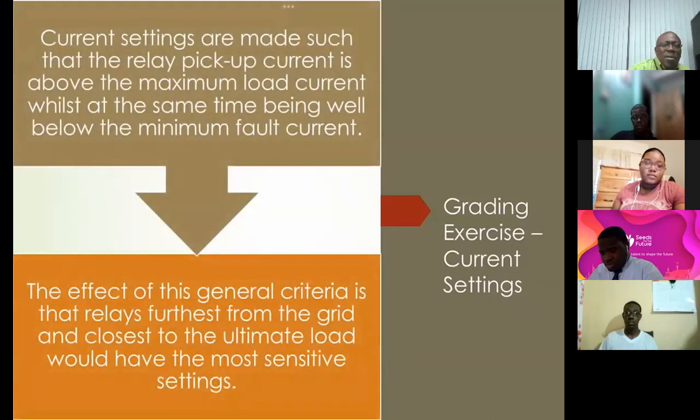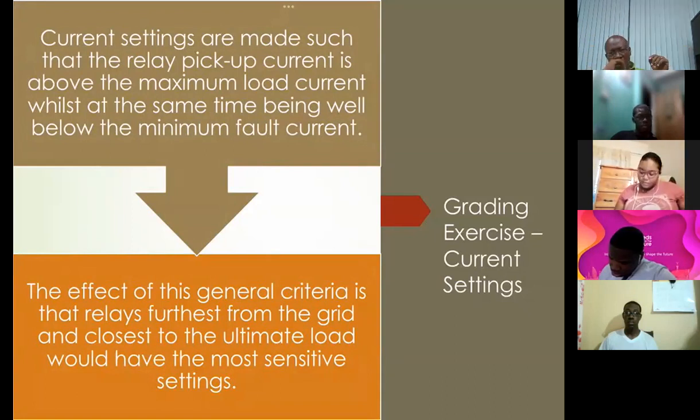So remember we spoke about discrimination, right? Keep in mind that we have already spoken about this. You want to ensure that the current setting is such that it is above maximum load, while at the same time below minimum fault current. So it must be above load and below minimum fault current.